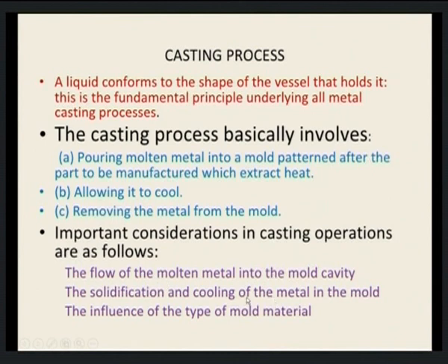The solidification and cooling, how fast or how slow the metal cools inside the mold, and then the influence of the type of mold material, whether the mold material is aluminum or steel, because there are a lot of heat transfer issues that take place when you pour hot molten metal into another mold cavity, which is again made of another metal. So, these are the general considerations in casting, but in polymers casting is dealt with in